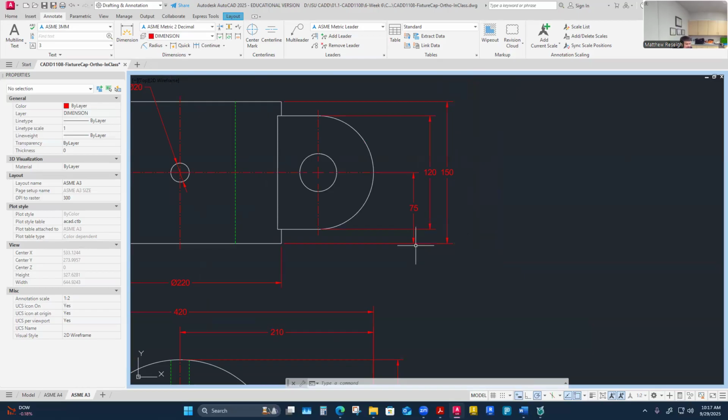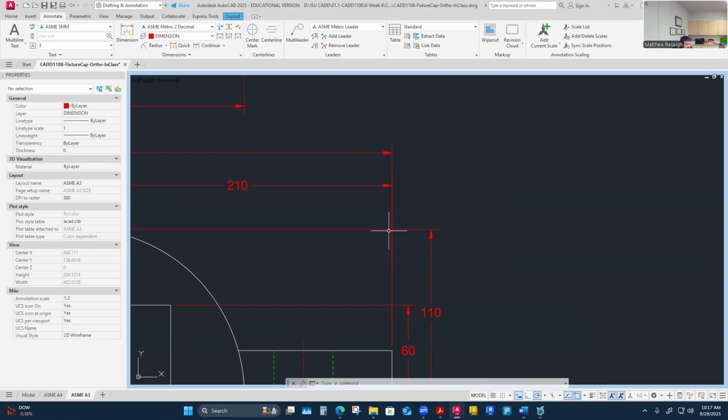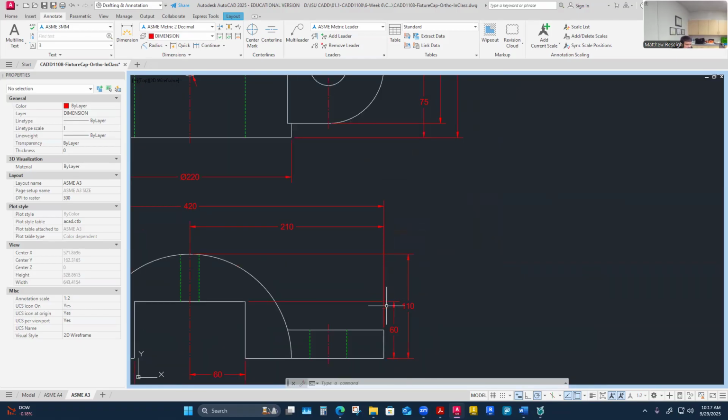When it's two extension lines over the top of each other, it doesn't matter which one I break, which is what's going on over here. These are extension lines crisscrossing. I could break either one of those. Sometimes I'll do the same break in the same view. So if I'm going to break the horizontal one, I'm going to do it on both of these where they cross.